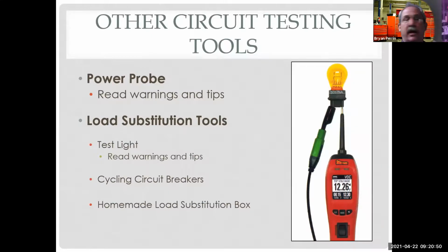Now, if I don't use it right and understand the wiring schematic, and I put ground where there's supposed to be power, or power where there's supposed to be ground all the time, we can let the smoke out of something, or I can kick the breaker on the meter. And that's why it's important to know how to read wiring schematics before we just start applying power and ground places. But this is a great tool.